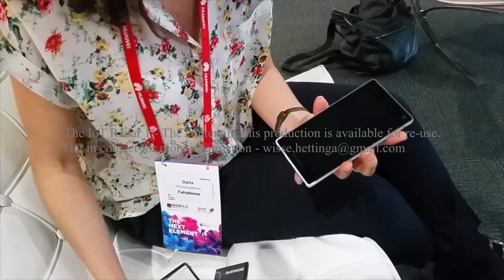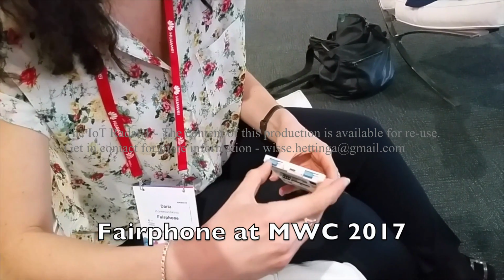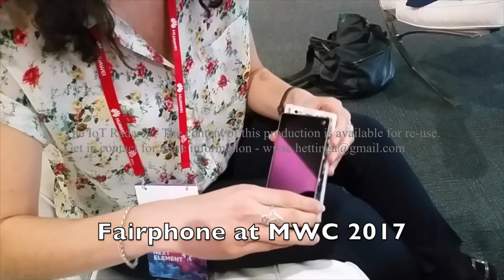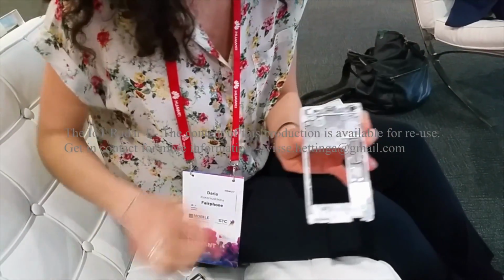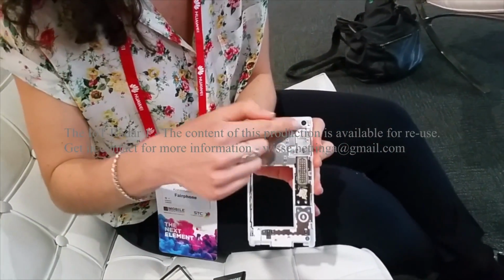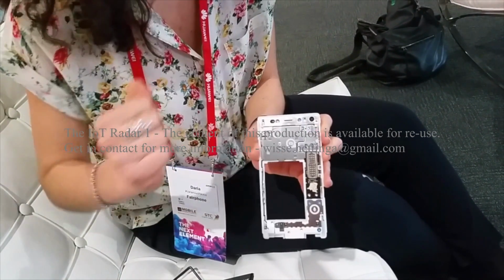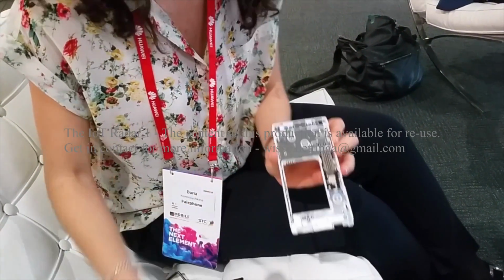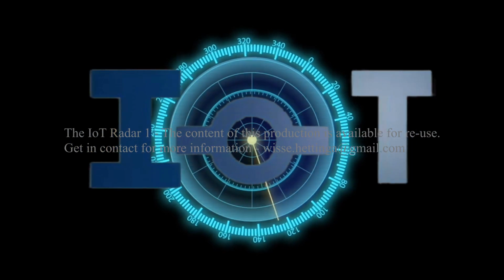And the part that breaks most often is the screen. So with Fairphone, we made sure that it's very easy to replace it. You can unlock it here, and then you slide it off like this. Okay. So that's a separate screen module that you can replace. And inside it's also modular construction, so you can replace the camera module, for example, by just unscrewing these 3 screws. You can replace top module with the headset jack, with the front camera, flash. So basically I don't need to go to a special shop. I just order a new component and take a screwdriver and replace it.